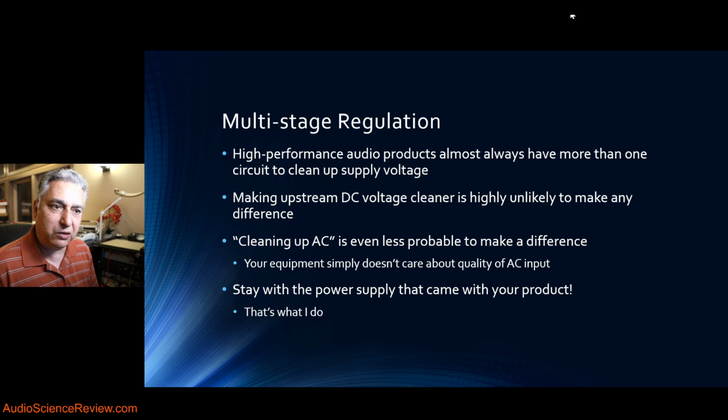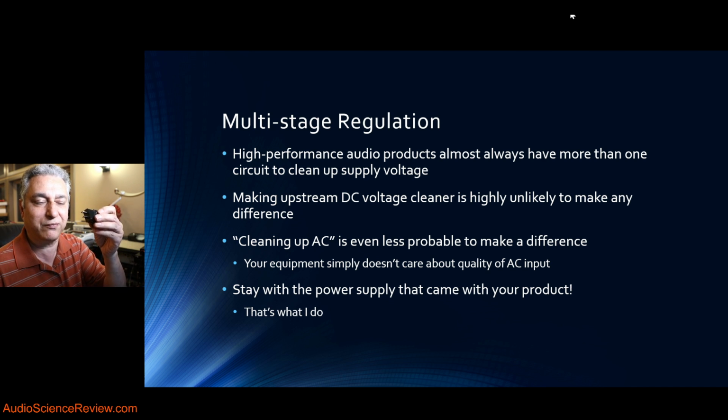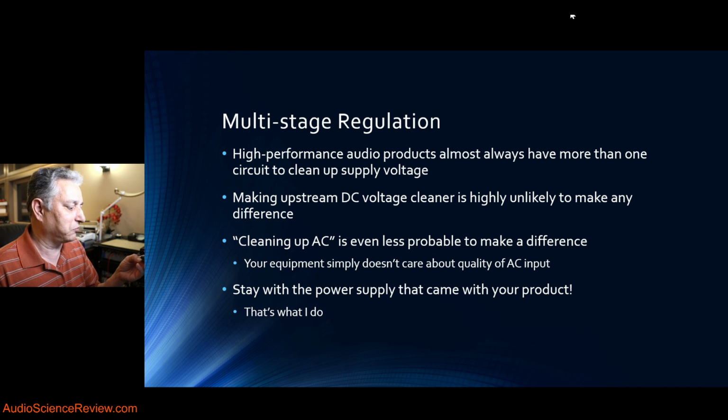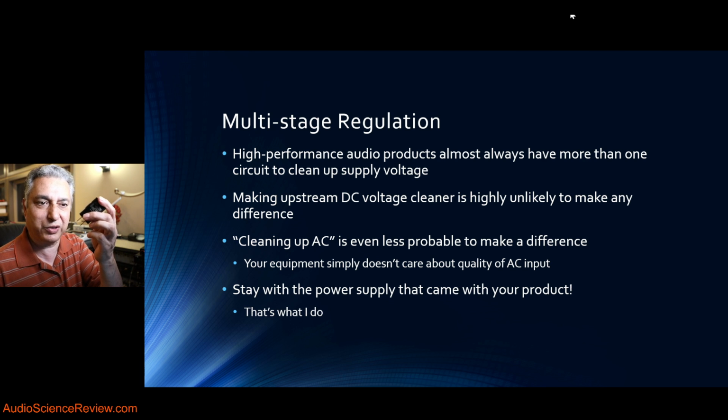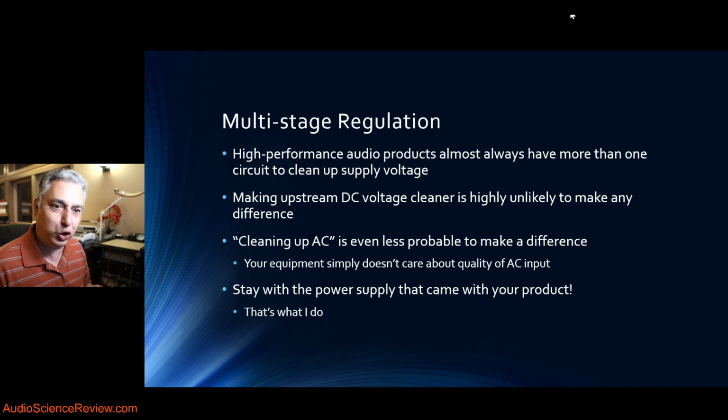I made a mention of this earlier, that your devices do have secondary and tertiary and even more regulations internally. So don't assume just because you can go get another 5-volt power supply that's much bigger and fancier and costs $500 that you're going to get better performance internally. Most likely, if the device ships with this, I measure it that way, and if I show you fantastic measurements, it means you don't need to muck with this thing. The same dirty external power supply is good enough, and it's good enough because internally they made sure they clean, they wash the dishes multiple times to get them very, very clean.